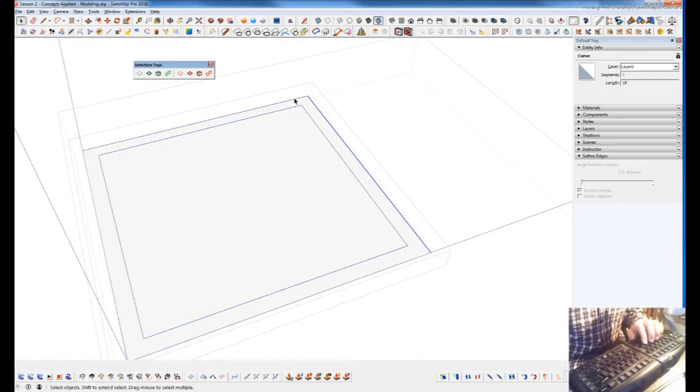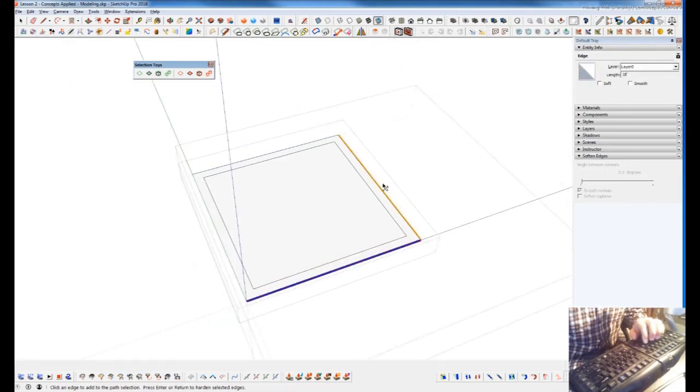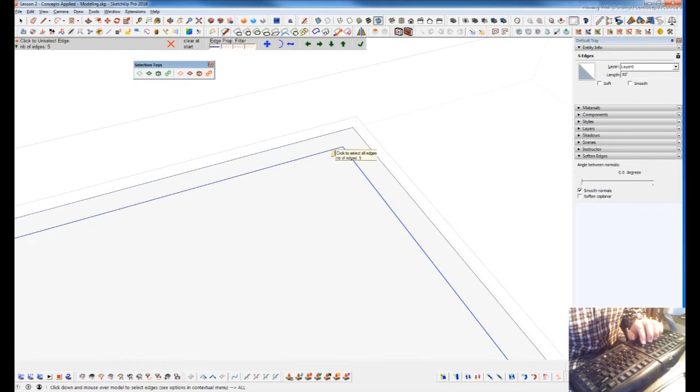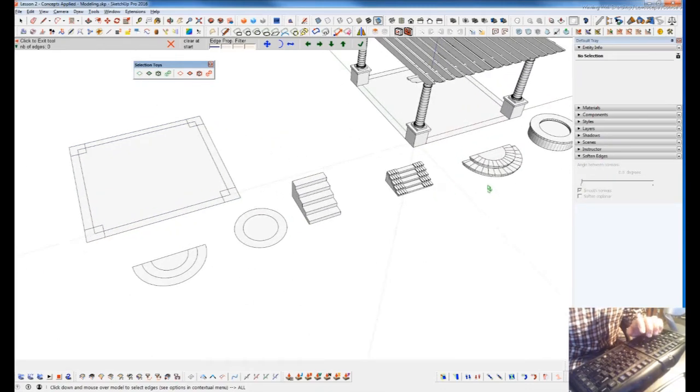And you can set these edge properties to extend to curve, things like that, instead of going through and clicking all of these. Or with path select, you're kind of going around this way. With hover select, when I had the keyboard shortcut, now I can just get in there and click and drag. There's a couple different ways that this will work. If I select the face, it'll select the outer and inner edges, and it'll give you some visual indicators showing me a minus sign. Now I'm deselecting.